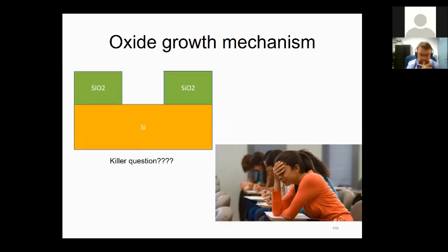So that's why I asked this very simple question to my graduate students here, and unfortunately it's only a few can solve this very simple problem. I tell them, can you show me the new pattern that we will get if we grow a thin layer of oxide, a thermally grown oxide, let's say 100 nanometer on the top? The numbers are not critical, but mostly they just draw this all equal and dull. That's not the answer, right? Because remember, we will consume the silicon underneath.